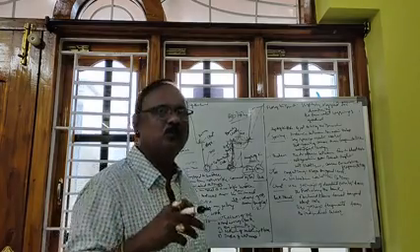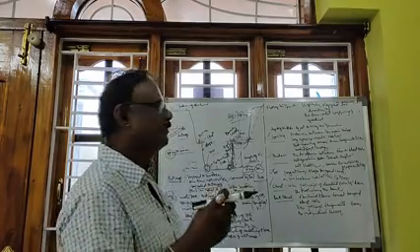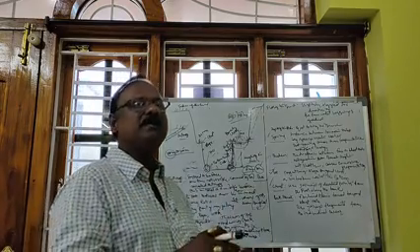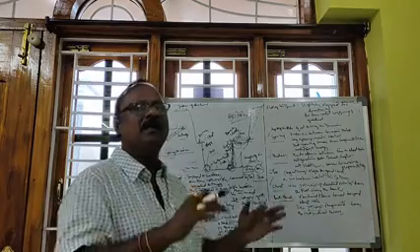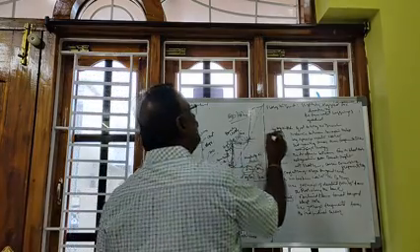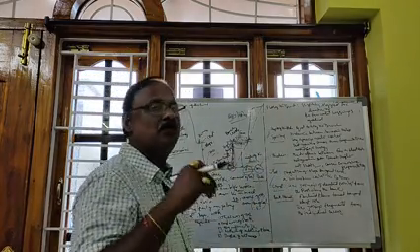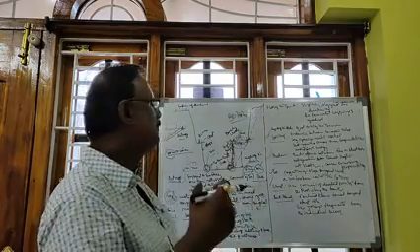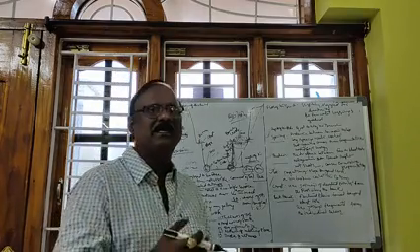Suppose the spacing is very much more, a crater is formed, and unbroken, unfractured rock remains there. That is what happens when we use a bigger spacing. When the spacing is shorter, excessive fragmentation occurs.